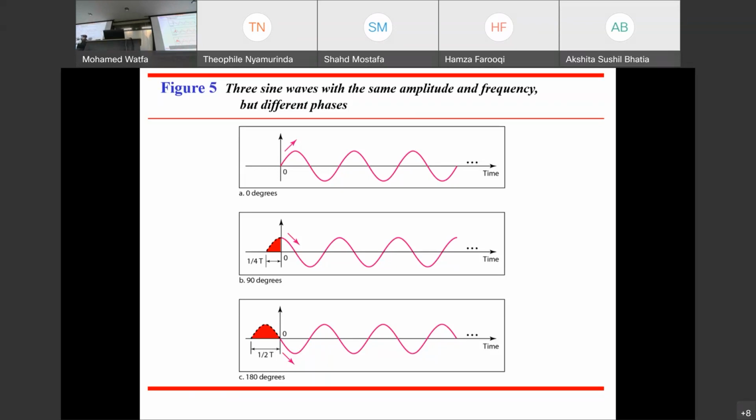Again, it's easier for you to understand. If I want to get this picture from this one, what should I do? I need to hold it and push it forward by how much of a cycle? By a quarter of a cycle. I need to move it forward by a quarter of a cycle to get the original sine wave. Therefore, my phase shift is plus pi over 2 or 90, which is 360 over 4. That's how we got it. Does that make sense? I could cut it smaller if you want, but typically we cut it on a symmetrical basis, like this.